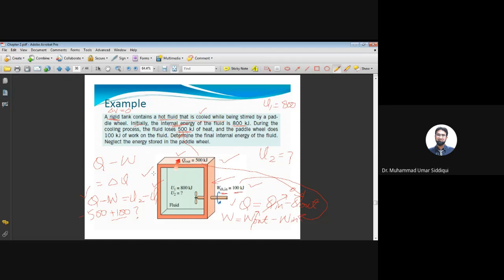The simple problems which I want you to solve do not need the advanced options. Okay, so you just need to write the equations and then solve them by placing the units, that's it, get the answer. And for whichever parameter you need to do the parametric study, you need to comment or put that variable in parentheses, and then generate a parametric table for the parametric study. And once you have the parametric table, you can draw the plot easily.